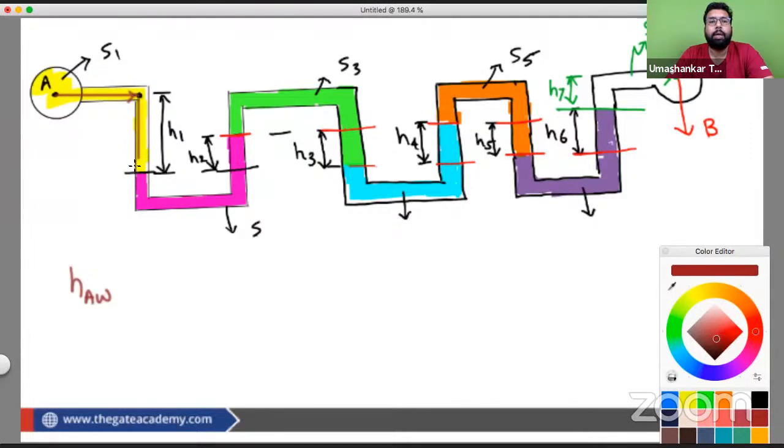Now in the downward direction, we can add it up, changing everything to water. So H1S1. From here to here we can directly jump, because if in the same fluid we are moving by the same distance, we shall not be writing anything. From here to here we can directly move up.